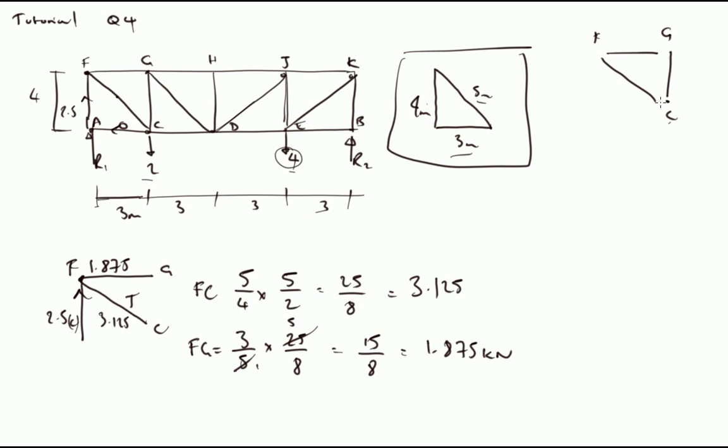So we're looking at this joint here, so we need to consider this CA, which we know to be 0. So resolving forces at C, then we know that we have 25/8 here, and therefore GC has a vertical component where that is in the ratio of 4 to 5, so 4/5 of 25/8. Again, these cancel 1 and 5.